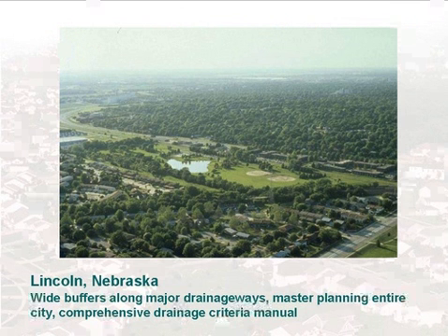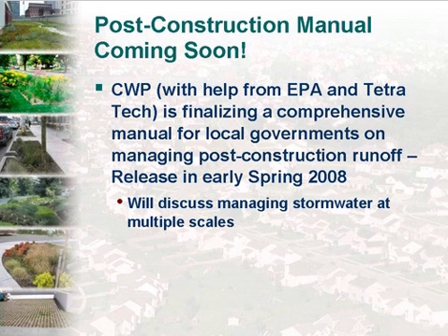Yeah, and particularly the greenway idea or the buffer strip, or whatever terminology you want to use, those are really BMPs that exist on a broader scale. If we're doing better planning to direct development into certain places or to redevelop underutilized parcels, and we're using conservation easements or buffer requirements to maintain some of these critical areas in our watershed, those are really BMPs too. They're not the kind that we often talk about, but in fact, they are BMPs, and as we said in the previous slide, land use is really the first BMP that we should all be thinking about. So that's one of the things that we want to talk more about in the future, so this is just here as a teaser for right now, just to make you aware of that.